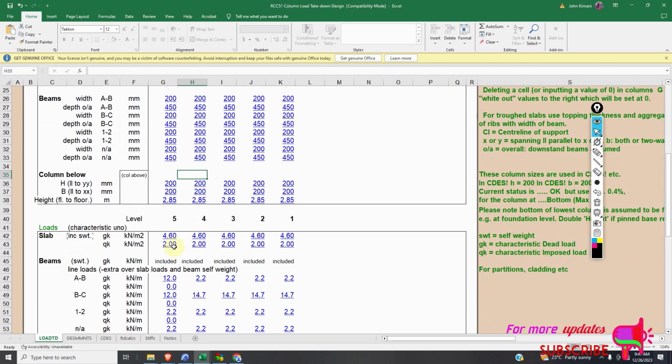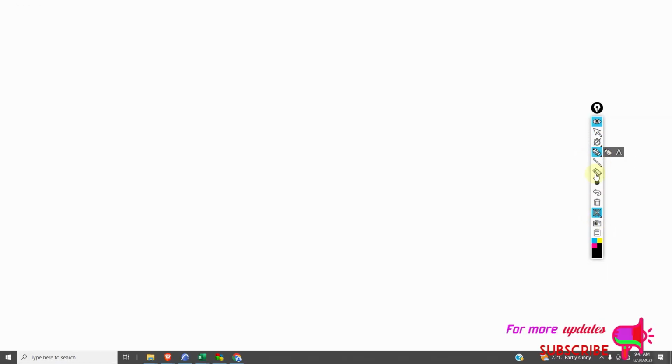Right. So our load on the slab is going to be the self-weight of our slab plus the dead load, that's Gk, plus the finishes and the partition wall. So we know how to calculate the self-weight of our slab. The unit weight of concrete is 25 kilonewtons per cubic meter, and we know that the depth of our slab is 0.15, or 150 millimeters.